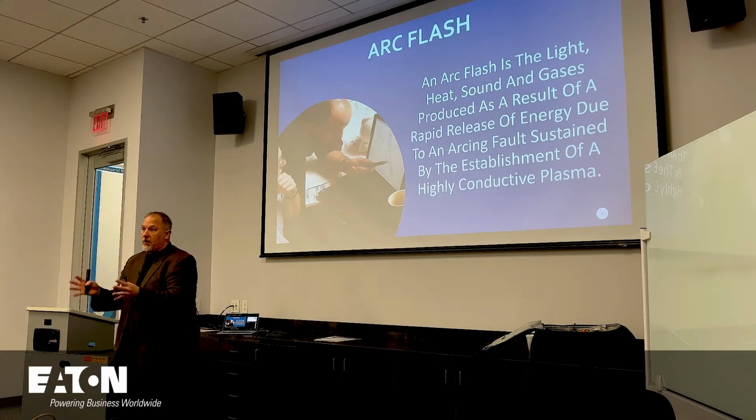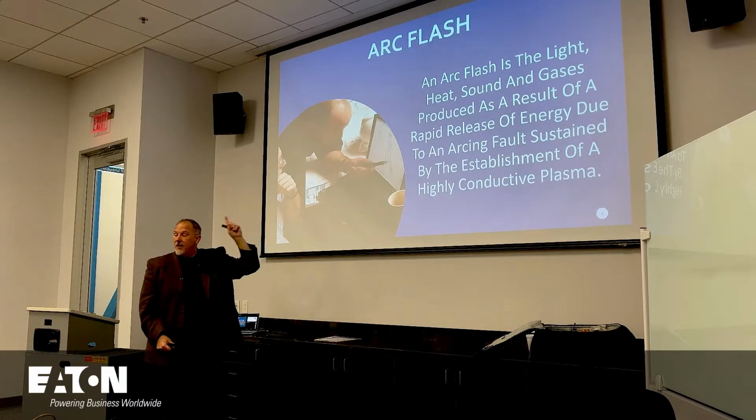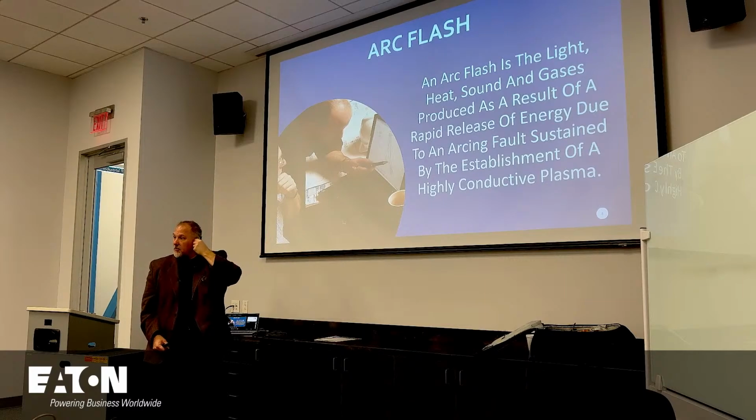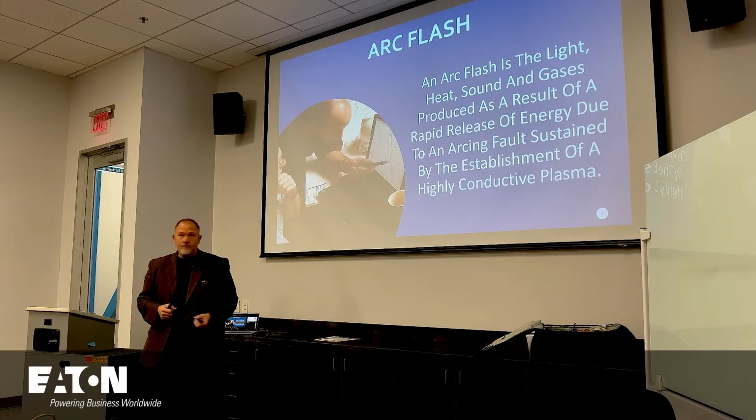But we can calculate the calories per centimeter squared, the heat only, although there are a lot of other components that are a part of an arc flash event. That's why we have personal protective equipment. We still have to have our ear protection. The shields and whatnot are tinted so that we can protect our eyes from the ultraviolet. It's like watching arc welding, right? You don't want to watch a weld go on without protection.